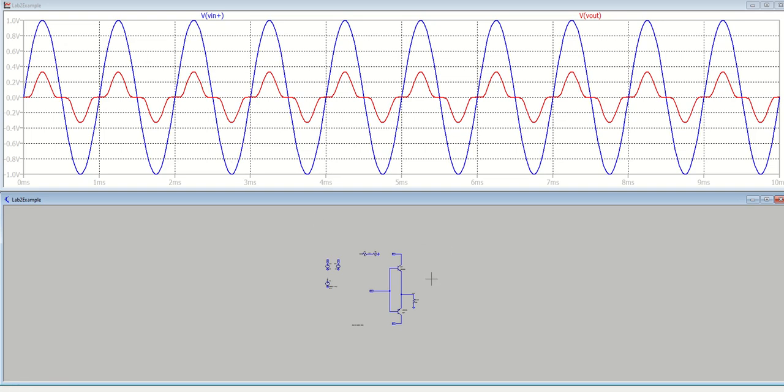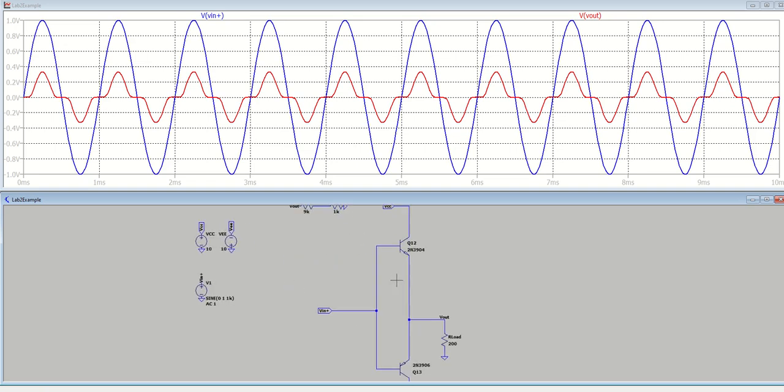So I'm not going to show you how to do it, but I would recommend looking up Class AB amplifiers. What that is, you're just adding 0.7 volts DC on the base of each transistor so that the input voltage is seen at the output without having to reach that threshold voltage. Okay, so Class AB amplifiers, check it out.